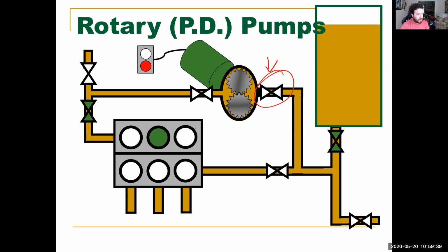So turn your pump off, and the pump's going to turn off. It's not like you have to wait for these things to slow down. They pretty much stop. They're not instant, but it's kind of like a car going from 60 to 0. It's pretty quick, it's not like it's a train having to slow down. You stop the pump, you close the valve so you don't allow any backflow.